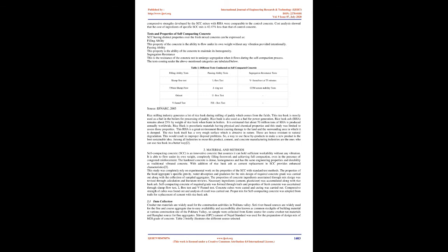Self-compacting concrete is a highly flowable type of concrete that spreads into the form without the need for mechanical vibration. Self-compacting concrete, SCC, is a non-segregating concrete that is placed by means of its own weight. The importance of self-compacting concrete is that it maintains all concrete's durability and characteristics, meeting expected performance requirements. In certain instances, superplasticizers and viscosity modifiers are added to the mix, reducing bleeding and segregation.